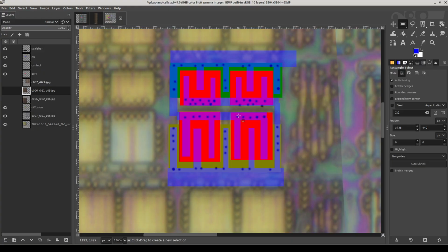Well, they're actually taking advantage of the parasitic capacitance of the MOS gate. So we have this large area of poly that is separated by an extremely thin dielectric, probably a few tens of nanometers would be my guess at 350, although I don't actually remember where the Dennard scaling was at that point. It's an extremely thin dielectric separating this poly from the substrate, so we have a fairly high capacitance here.